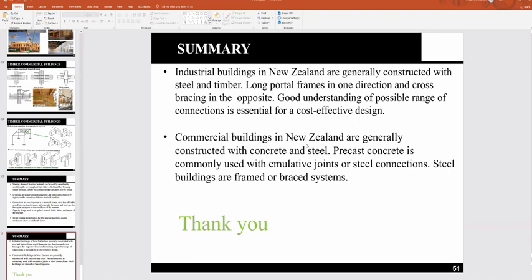What is the static load for a timber structure and what is the deflection for timber? Load is a load. It could be dead load or live load. It's not different whether it's timber or concrete. But generally we limit deflections with a stringent criteria for timber structures because there is a high chance of failure, which is a brittle mode of failure.